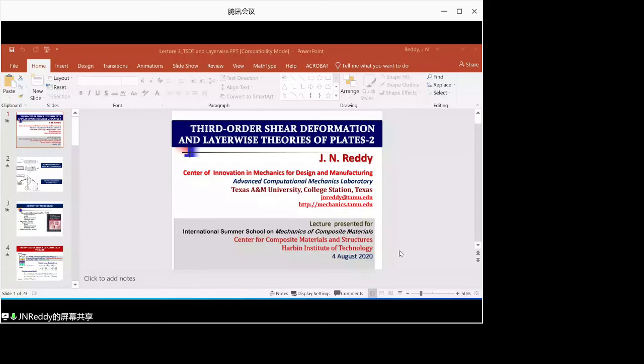That is where layer-wise elements are much cheaper, yet they have the same ability as three-dimensional elements. In place of a refined mesh, you will use a refined element, meaning an element of a different kind. It's not the same plate element, just smaller. That won't do the job, because no matter how small you make the element, it does not bring the three-dimensional effect.